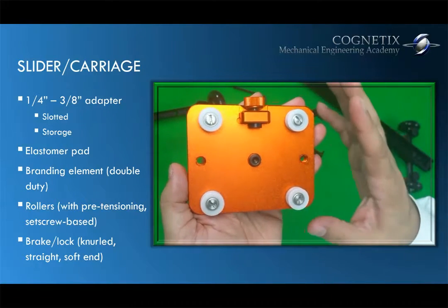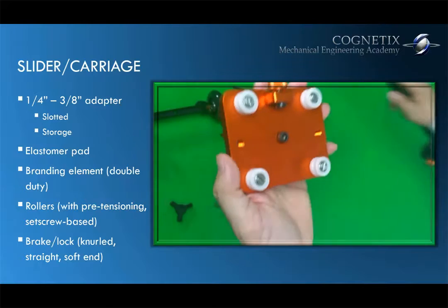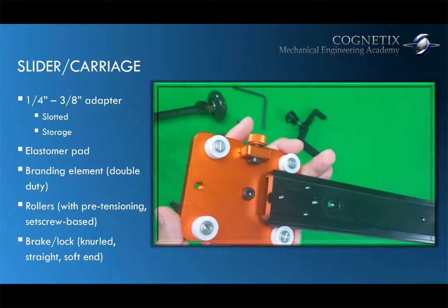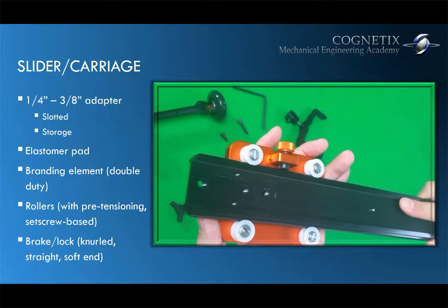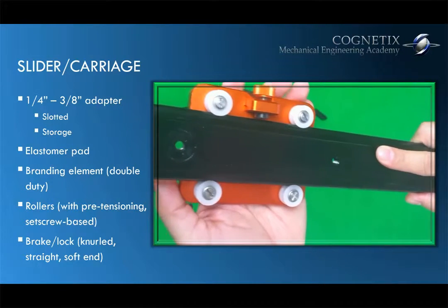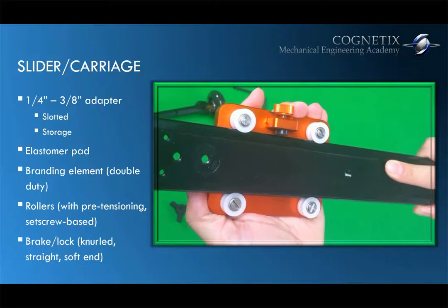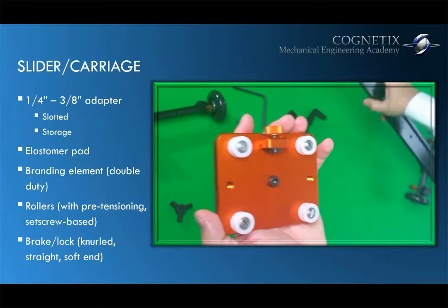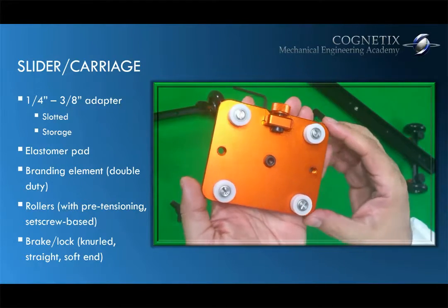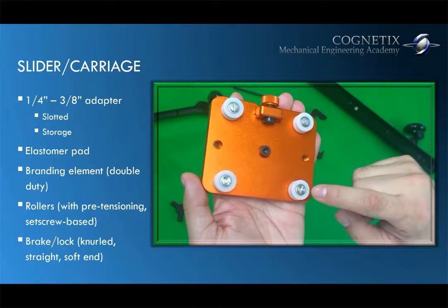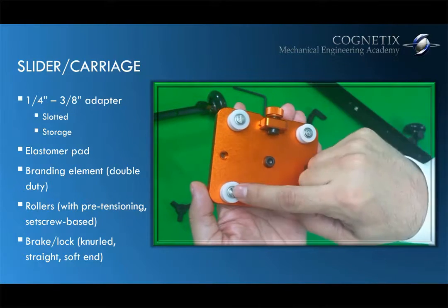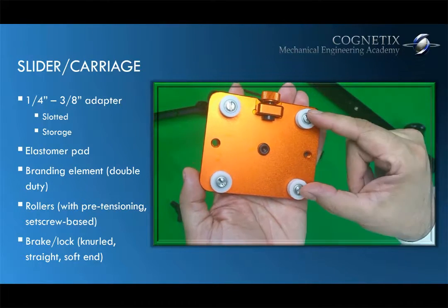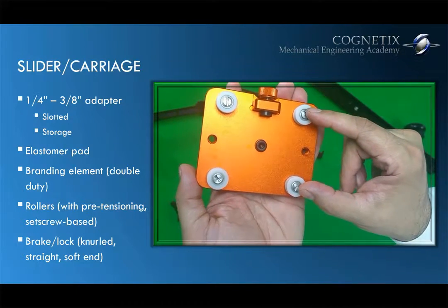Okay, so the reason I bring this up, this carriage design fits very, very nicely here. If you're able to see it, I cannot wiggle this in any kind of way. It's secure. Okay, so we ask ourselves, how is that possible? If there is a manufacturing tolerance between the axes of these 4 rollers, let's say from here to here, let's say it's supposed to be 2.75 inches.